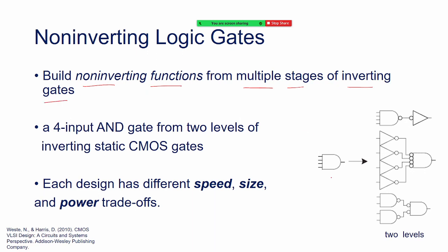So I want to make this AND function right over here, AND logic. I know that I have these 4 inputs. We have seen that in previous classes also. There are ways, but you'll see now there are always 2 levels. So I'll have to invert the signals. I can't really swap the pull up and pull down network and go for it.